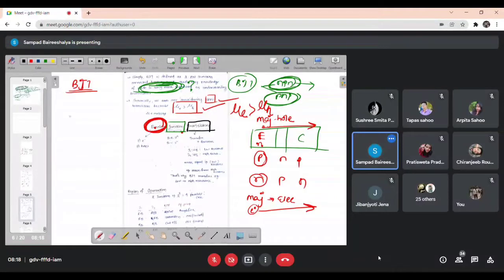In reverse bias it is high. So junction 1 is forward biased having low resistance, and junction 2 is reverse biased having high resistance. That means you are changing the resistance from low to high. That's why it's called transfer of resistance.